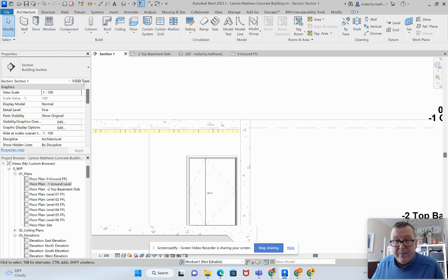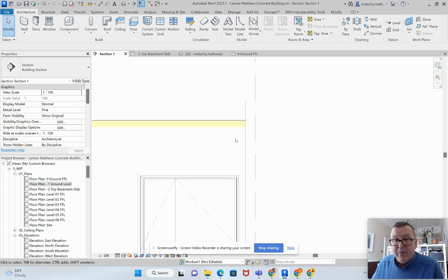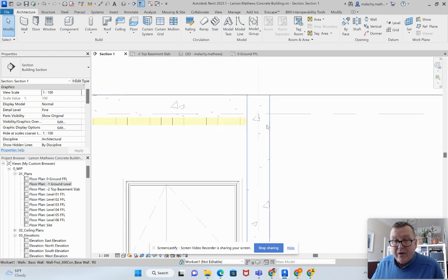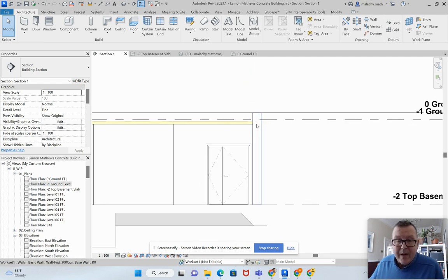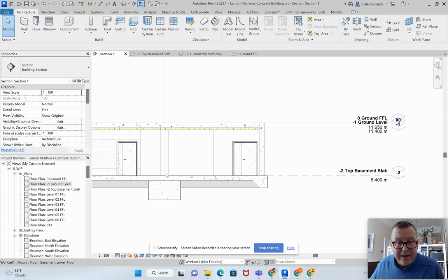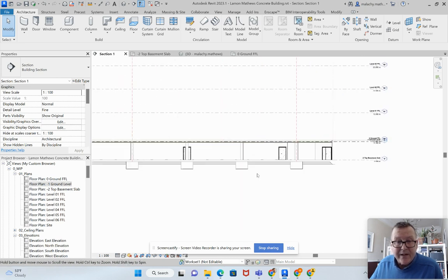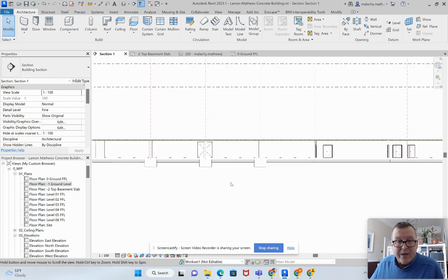You would have the floor, this floor would probably be cast in on top of this one, and you'd have starter bars and all that stuff coming in here. But what I don't want is my insulation coming across here either, because insulation is not structural, so the insulation starts there. But if you remember, it's on the same principle here, that all of this will be a homogeneous piece of concrete, and as will that there. So I think that gets out of that kind of situation pretty neatly.